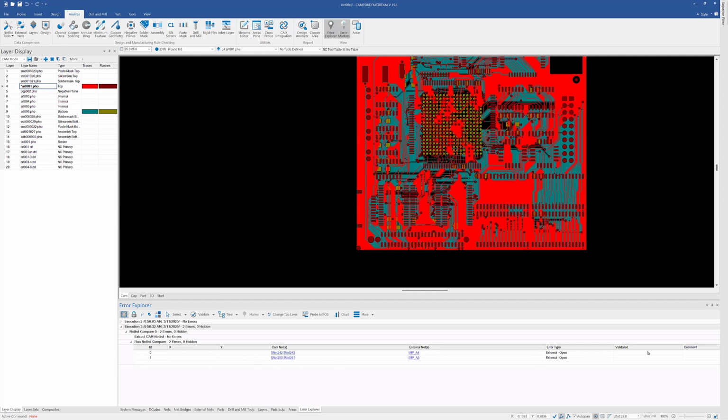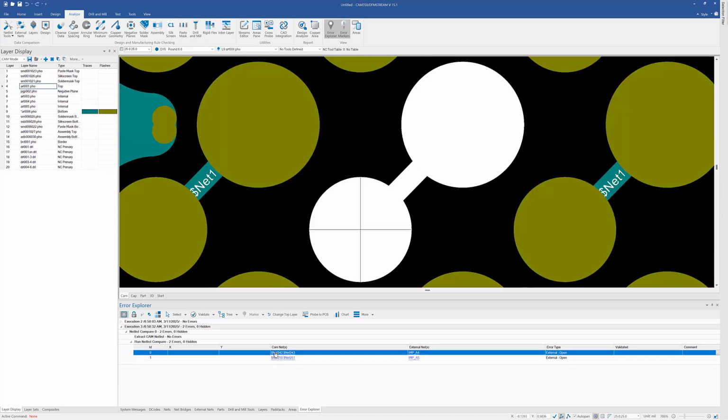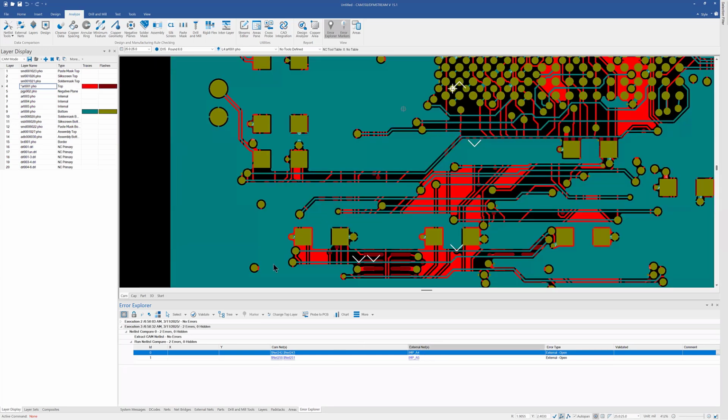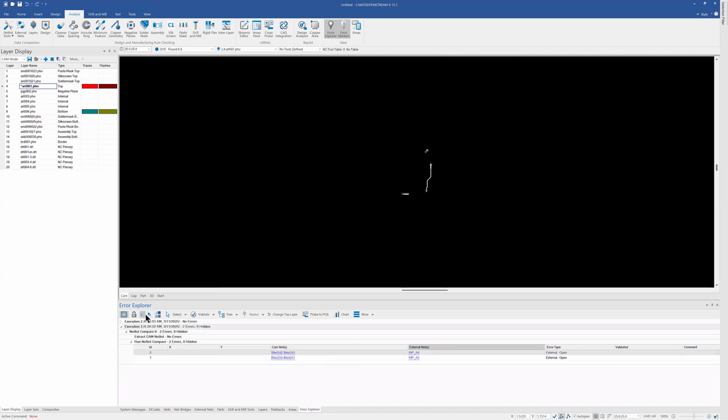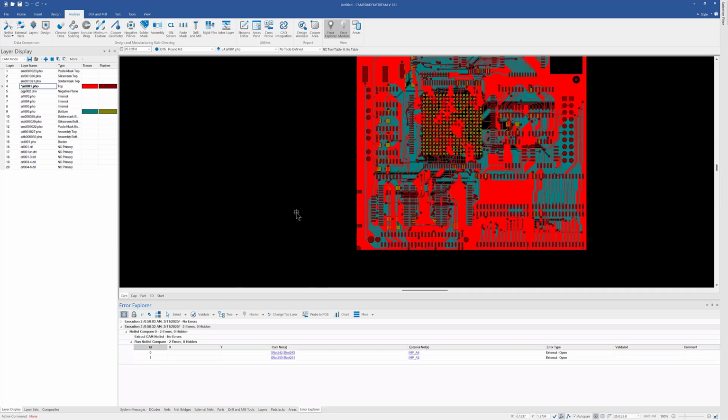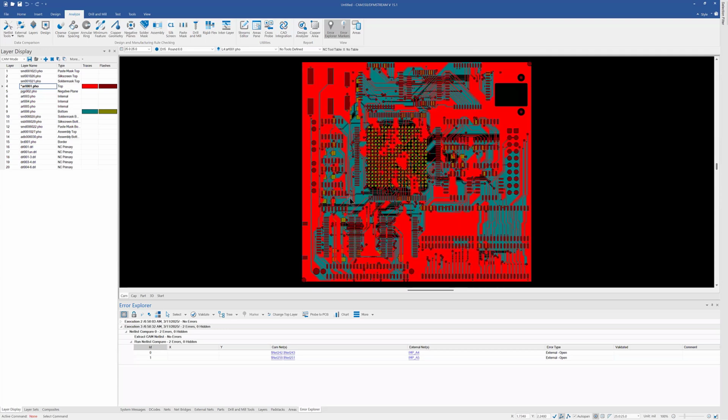We've also put hyperlinking in here. So this was an open. My Gerber extracted nets were 243 and 242. My IPC net list was this A4 because it's an external net. It's just showing me the points. But I can use this hyperlinking to help me figure it out as well. What I'd probably do is use it in conjunction with the isolation or the low light mode. Okay, and go in and look at those. All right, so those are all designed to help you with net list comparison, and they've come in recent releases as well.